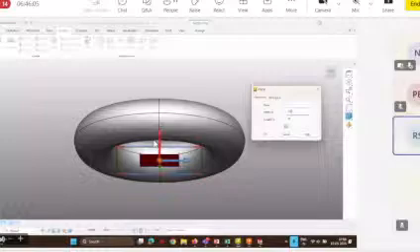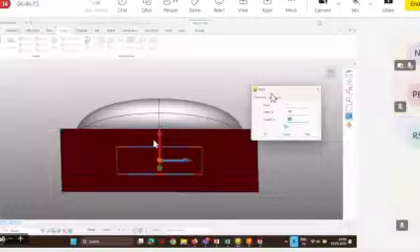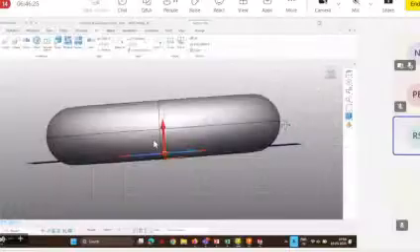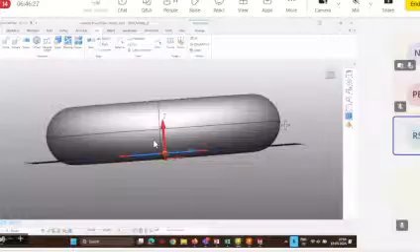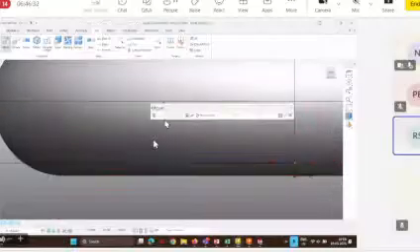Click OK, and now I'm going to move this. Maybe this is my slicing height, and just to define its angle, we can get another slice just above it. We can do move, copy one, a very small distance above it.